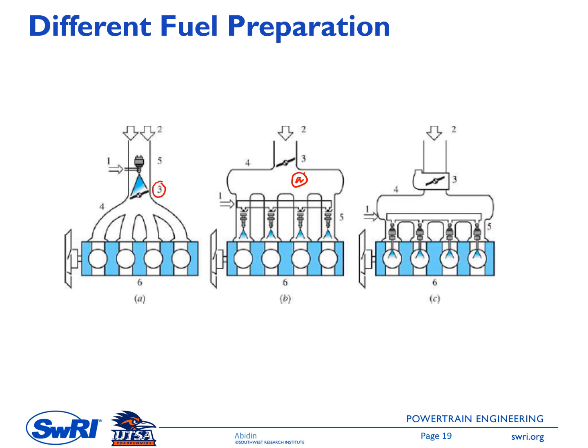In schematic B here, we have one injector for one cylinder, and this configuration is called port fuel injection, PFI. You might see this PFI on a car body or somewhere in the engine. The schematic is shown in this B.